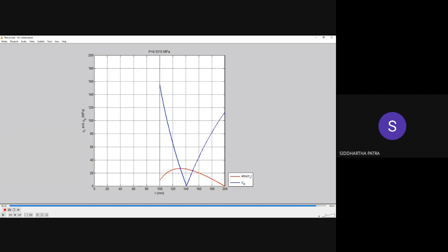So with elastic loading and elastic unloading, each point within the material would be unloaded by the same amount of stress that it reached during the loading phase. So there will be no residual stress, but such is not the case with plasticity. Okay, I'm done with whatever I needed to show.